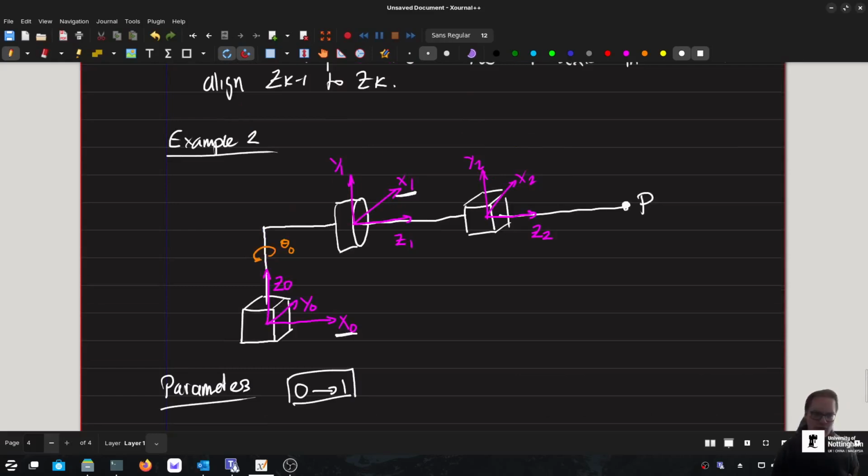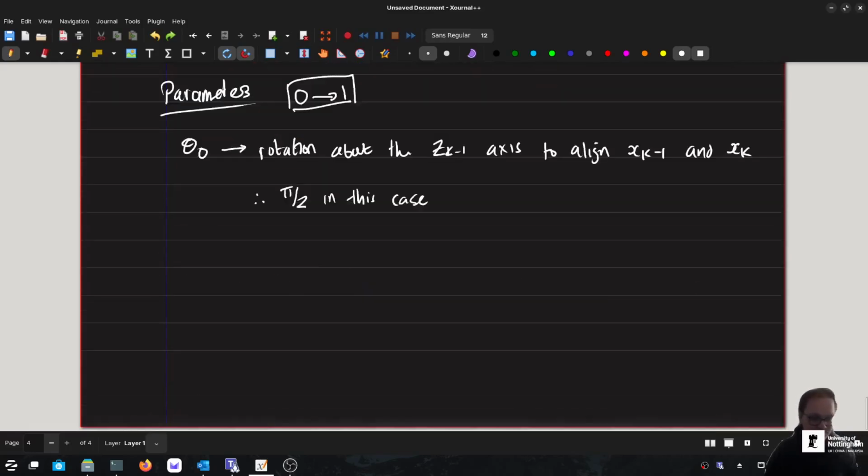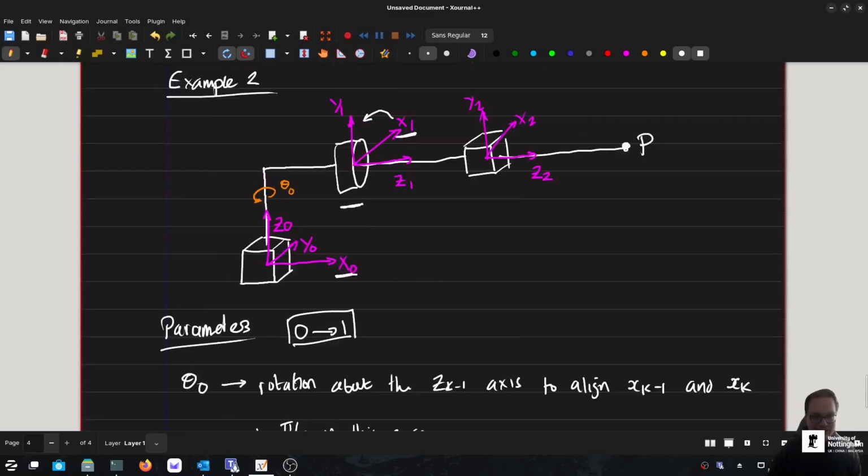So you could argue, well, this is a revolute joint. Technically, if I rotate the revolute joint, that x1 is also going to be rotating. Well, what we're looking at doesn't exactly affect the frame going from here to here, because we're looking at going from Z0, which is not affected by that revolute joint. That is fixed. The prismatic joint is always going to be fixed. The revolute joint can always change, but technically, from the perspective of the prismatic joint, x1 could be in any location. We just assume the revolute joint is 0 in this case. When we go from frame 1 to frame 2, then it does matter, because the rotation of the revolute joint does indeed change the next prismatic joint. But this one is not affected by the revolute joint, because it's not connected on the other side of it, if that makes sense. So we're just going to say it's plus pi over 2 for this case, to align the x-axes, assuming the revolute joint is static for our analysis for the moment.